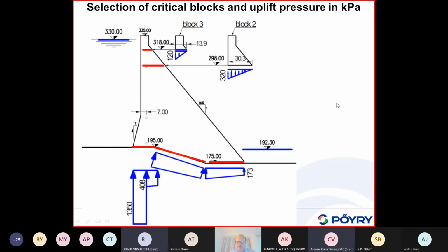That is a basic assumption. So what we have been doing is a dynamic stability analysis of these blocks, which are assumed to be rigid. Once we have cracks developing here, 95 or more percent of the displacement of this block is due to deformations along this crack, and not due to elastic deformations of the dam body.